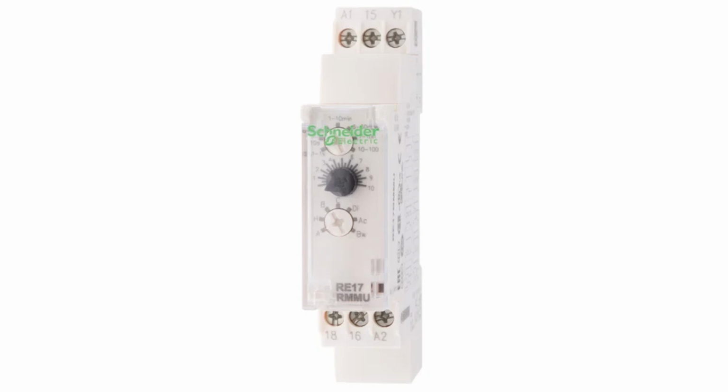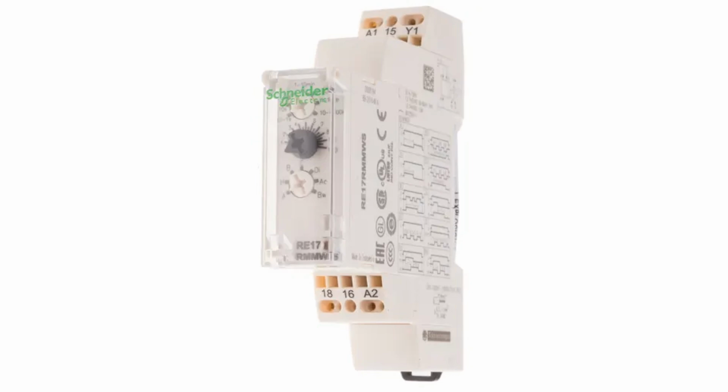Here's what you need to know about voltage and current ratings. Voltage rating. The voltage rating indicates the maximum voltage that the time delay relay can safely handle in the circuit. It's crucial to ensure that the relay's voltage rating matches or exceeds the voltage of the electrical system where it will be installed. Operating the relay above its rated voltage can lead to overheating, insulation breakdown, and potentially damaging the relay or other components in the circuit. Current rating.